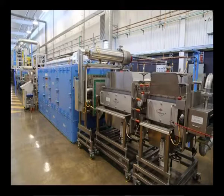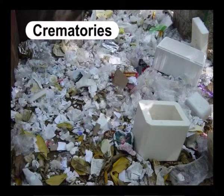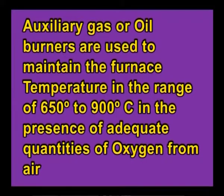Stationary hearth furnaces are used for most commercial and smaller industrial incinerators. They are also used almost exclusively in crematories and for hospital wastes. For the latter applications, auxiliary gas or oil burners are used to maintain the furnace temperature in the range of 650 degrees to 900 degrees centigrade in the presence of adequate quantities of oxygen from air, well dispersed throughout the